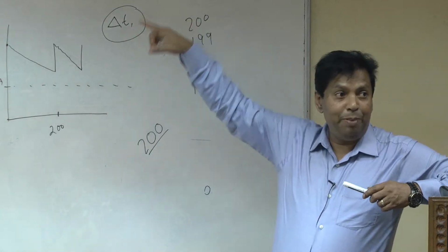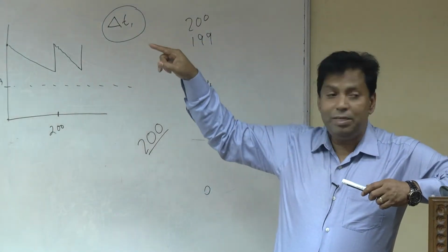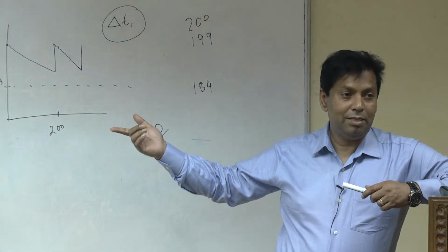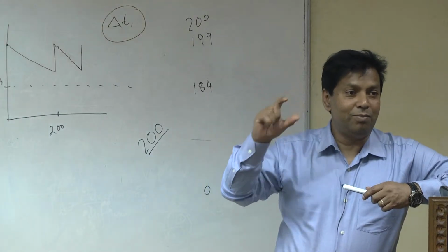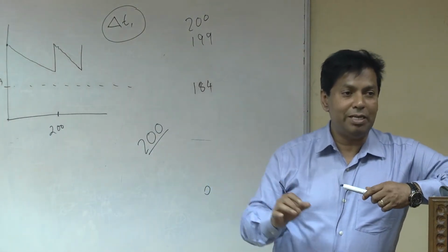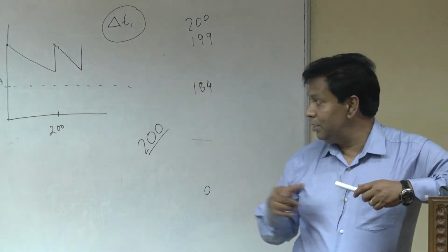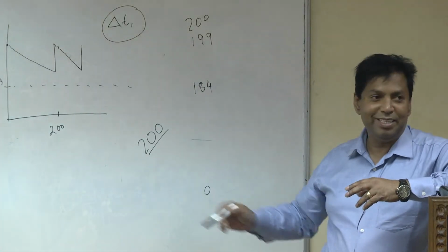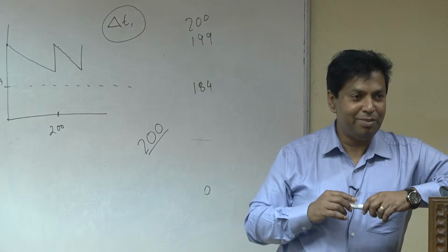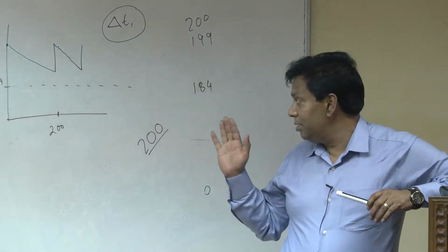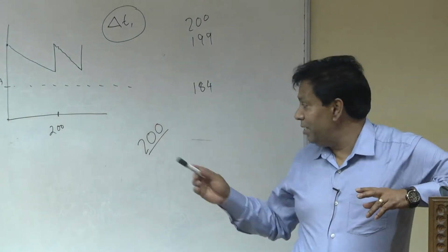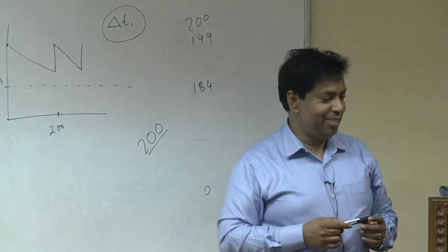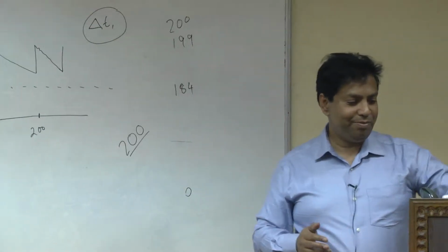There is a very big peak. I think at that time it will take more iterations. So it is not fixed that it will converge within 20 or 25 iterations. It will fluctuate, so it is always good. When I did my PhD, I always used 500. Okay, that's a safe zone, I just put it, so that my solution is converged. So if it is not converged within 500, definitely there are some issues, so I had to look into it.